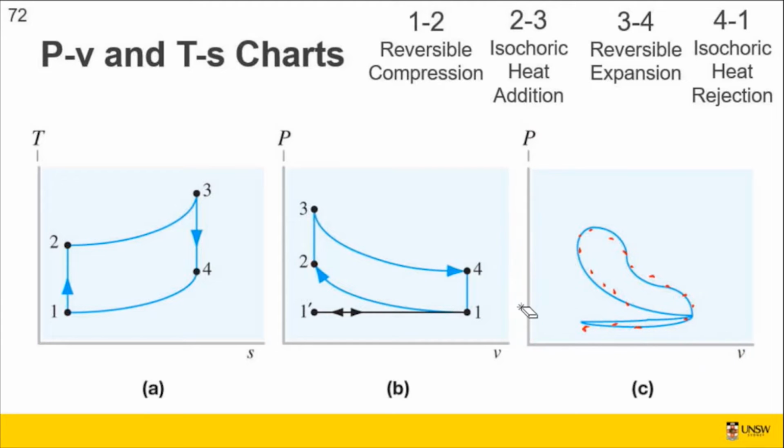This is something that I think it was James Watt was doing to improve the efficiency of the initial steam engines. He was obviously doing it mechanically, right? He had a pen going up and down on the volume axis and then allowed pressure to go along, right? So he was producing PV charts experimentally and saying, how can we get this more towards the ideal? So an actual track of the PV chart.